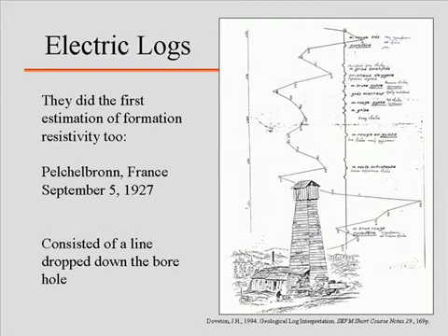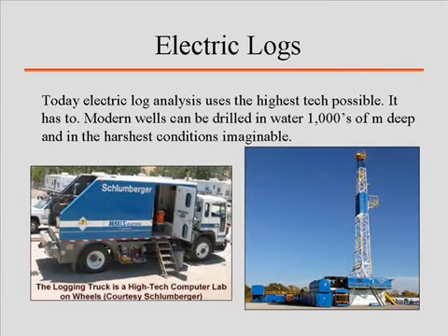All right? But I do know that what we do now is completely separate. We don't have measurements periodically. It's a continuous measurement. Now here's what we do today. It's gone a long way. Companies like Schlumberger, Dresser Atlas, or Halliburton, anyone you want to look at, have everything packaged up in really nice little bundles. So when you start drilling, and you're drilling your hole down, once you get down to the bottom of your depth, through your blowout preventer you can now start to access that hole. So what you need to do is be able to run your probes down from the top of the hole down to the bottom, or usually what they do is they drop it right down to the bottom and then they raise it back up, and then they give the responses according to what the depth is.